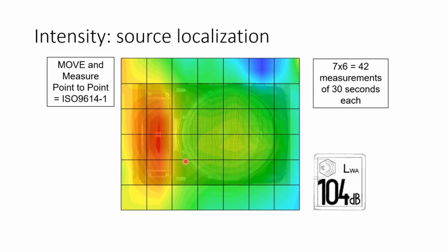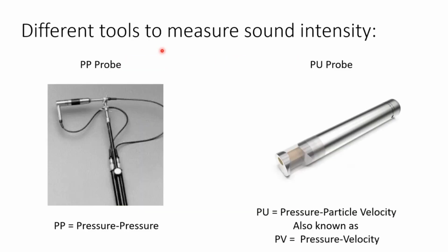Depending on what type of noise was played out of the speaker, I don't particularly know. I'm going to guess it's more high frequency since the subwoofer isn't really being utilized. Now, if you have something more complicated, this can be really useful for figuring out where your source is coming from and at what frequency. So if you want to isolate specific target frequency problems and find where those are coming from, source localization can be really great.